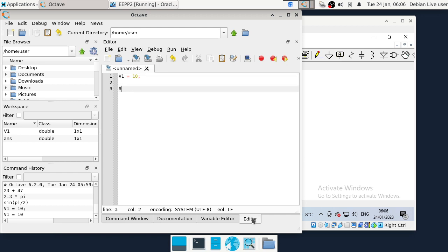We've got a couple of resistances here, so I've got R1 which was equal to 30 ohms. So I'll say R1 equals 30, and I have R2 equal to 20 ohms. So what can I calculate here? Well, there's a couple of different ways that you could do this calculation. I think what I'm going to do is calculate the overall resistance of R1 in series with R2. So I'm going to say R is equal to R1 plus R2.